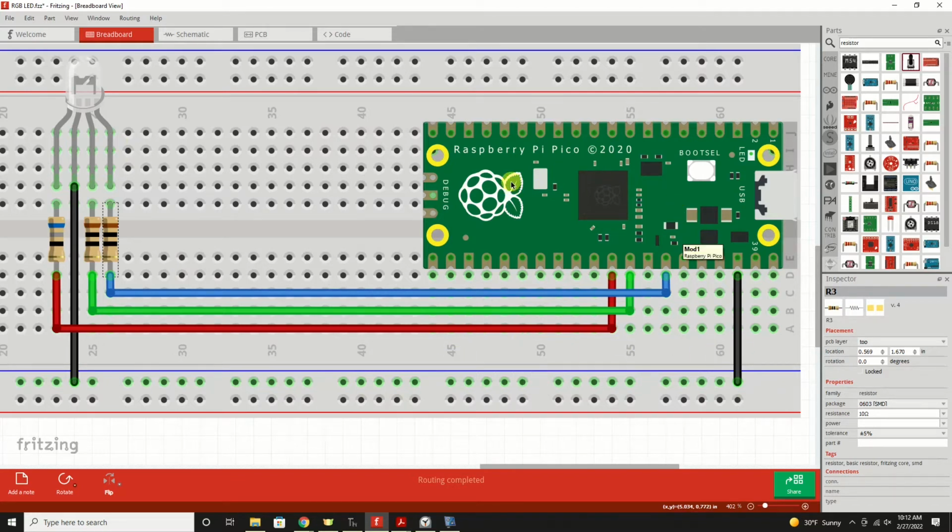Here we've got a Raspberry Pi Pico. This is our ground pin number 38. Comes down to our ground rail over to pin number 1. Now you might look at that very cleverly and say, hey, Chris, you got to wire it up backwards. No, it's just rotated 180 degrees. We're looking at it from the back side as opposed to the front side shown in the data sheet. So this one is my pin number 1, as it'll be laid out on the breadboard, the actual breadboard, as we'll see in a minute. So that's our 0 volt line.